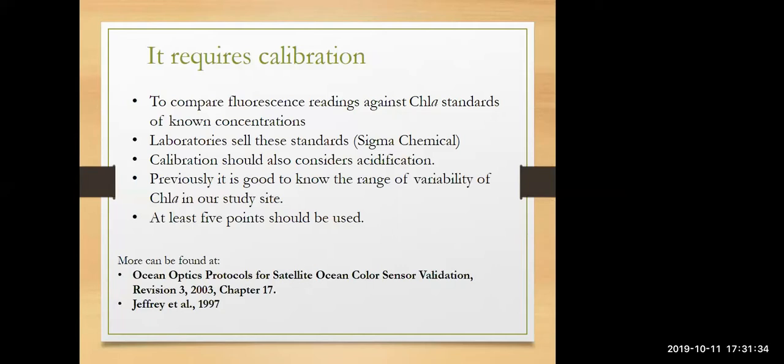Another point that I did not mention with spectrophotometers, but which is necessary when using fluorometers, is calibration, because we have to compare fluorescence readings against chlorophyll A standards of known concentrations to establish a correction factor for the fluorescence readings the equipment gives.